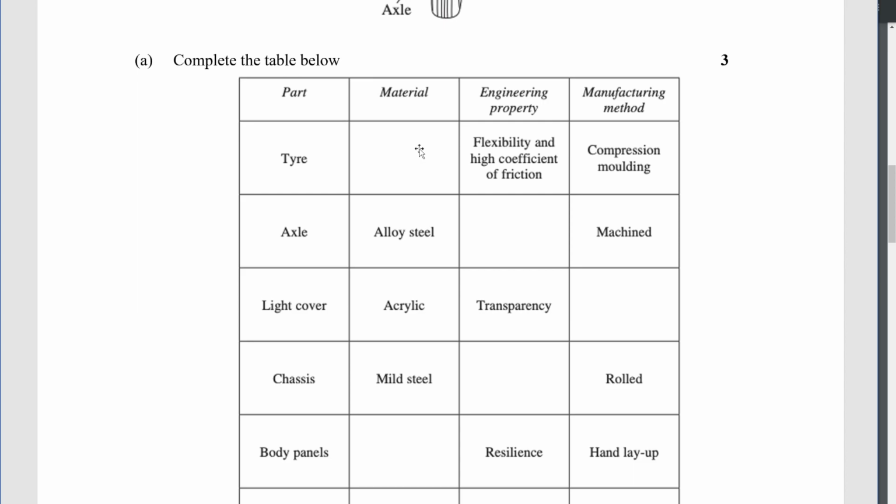High tensile strength would be an even better answer. But we could also say it has good high strength and good toughness. Toughness is important because that way it can resist impact. If they said machined, if you wrote machinability, I would feel as though that was a little bit of a weak answer, but I'd probably still mark it as correct. If you said plasticity, so the fact that it can be forged, it requires plasticity to do that. That one is definitely the most open in the number of options you can give.